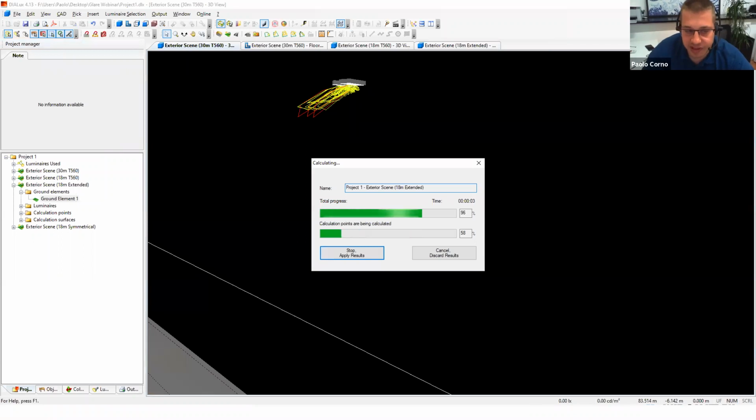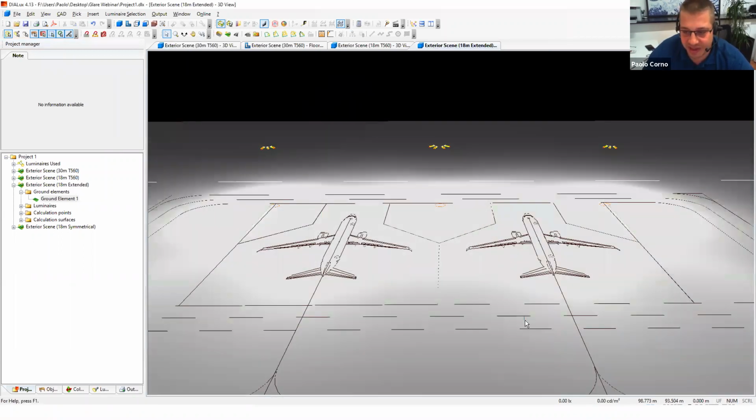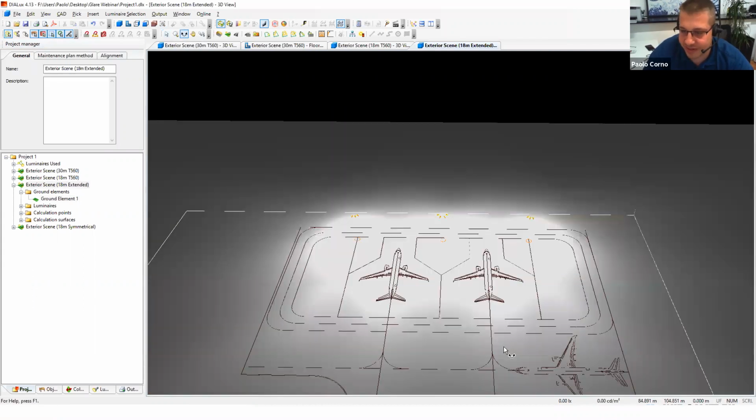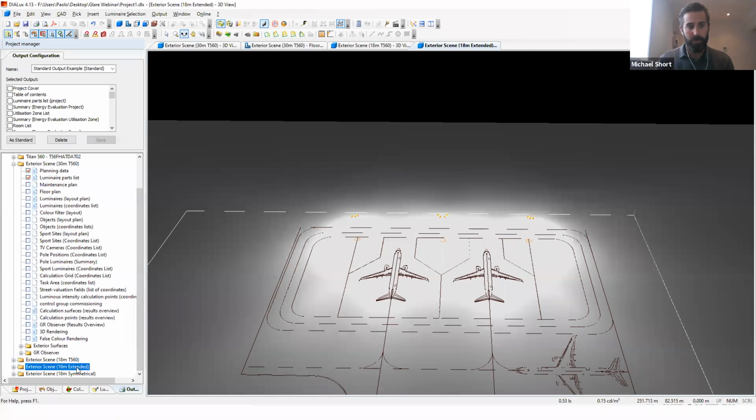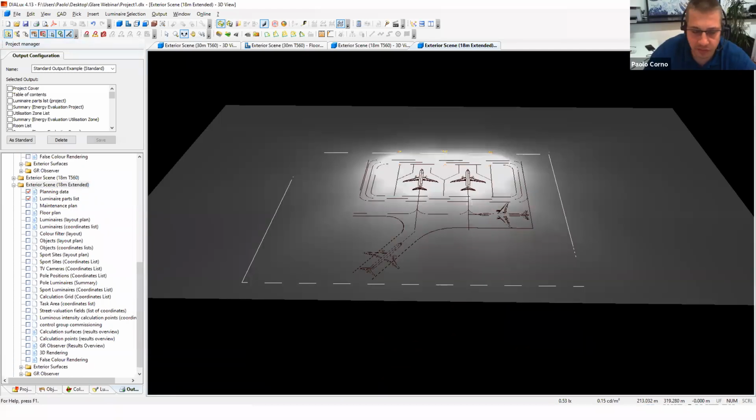But sometimes it will actually give you the opposite result of what you think, because your glare rating might decrease. The contrast of the background now becomes smaller, because the background has a higher luminance due to the higher reflection. Okay. Let's see, for example, I don't remember which one we did it on, the extended.